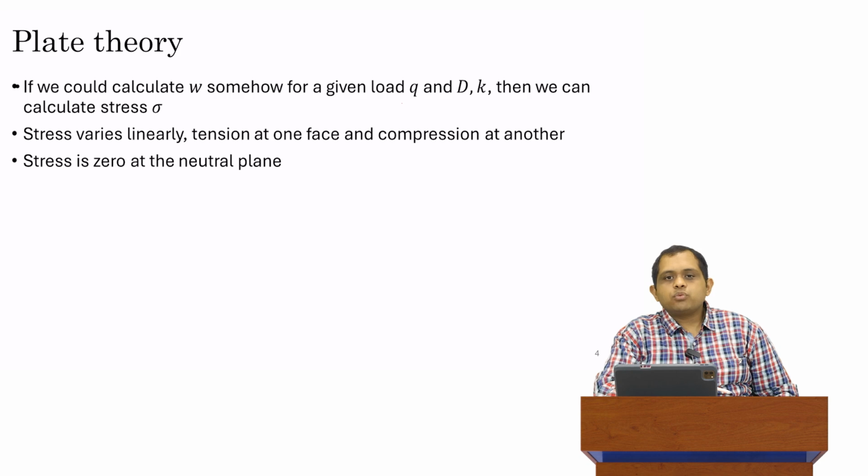The question is, it's well and good to have a differential equation. How do we solve it? So one thing to understand when we're solving it is as follows. Given some loading Q, given the plate properties D, given the subgrade properties K, can we calculate W? That's something we have to answer. But generally, we are not really interested in the displacement. It's good to calculate it, but that's not what we are interested in as civil engineers. What we are actually interested in is the stress. But the question arises then, which stress?